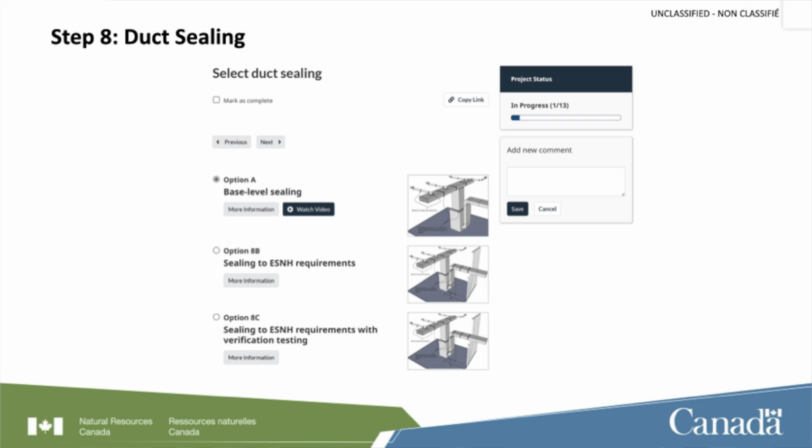And let me tell you, on old homes, it is horrifying. We can expect anywhere between 50 and 70% duct leakage on any home built before 2016. Around 2016 was when we started sealing things up better. And because we seal things up better, we're now in the 30 to 50% duct leakage. Okay? So that means that 30 to 50% of the air that we're heating is doing a great job, again, of heating a joist space somewhere, or a wall cavity somewhere where nobody lives, except maybe a couple of critters for which they are eternally grateful.